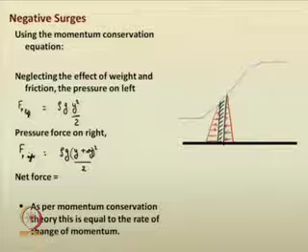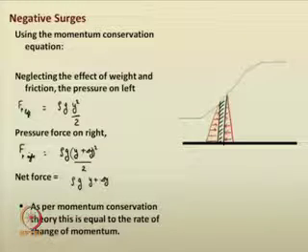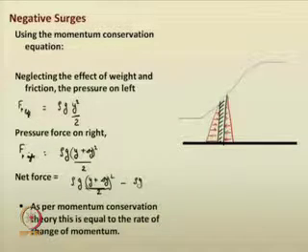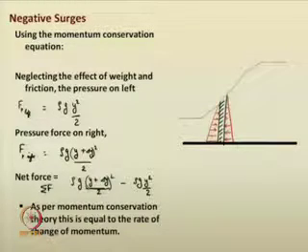So the net force acting is rho g times (y plus del y) whole squared by 2, minus rho g y squared by 2, right. This is the net force, sigma F, acting on this elemental strip.